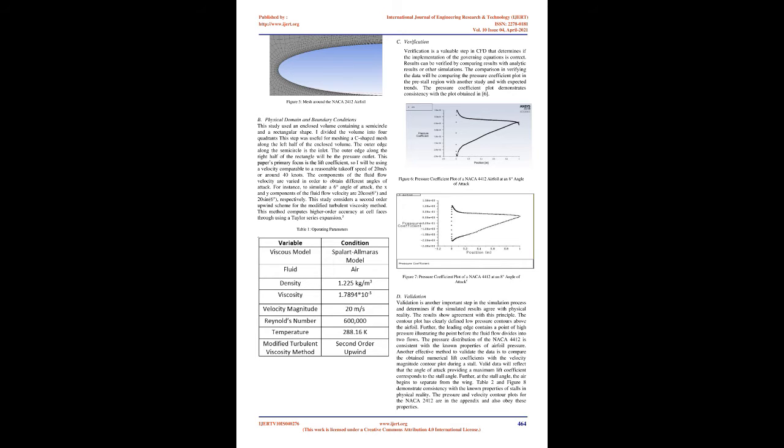D. The Spalart-Allmaras turbulence model. Turbulence models are mathematical models that predict the air's turbulence effects. These complex equations are often designed for specific applications. This study utilized the Spalart-Allmaras turbulence model, which was developed primarily for aerodynamic flow over an airfoil. The Spalart-Allmaras model is an eddy viscosity transport model.